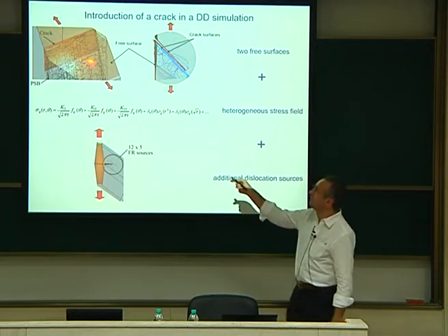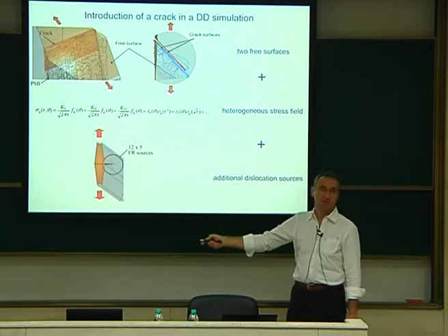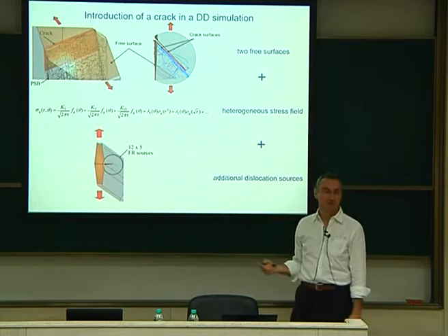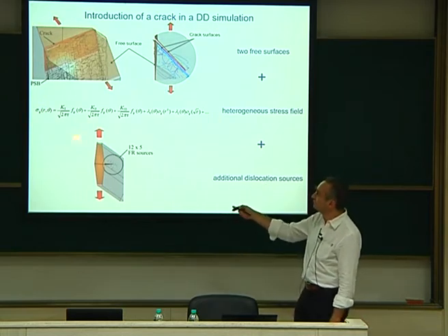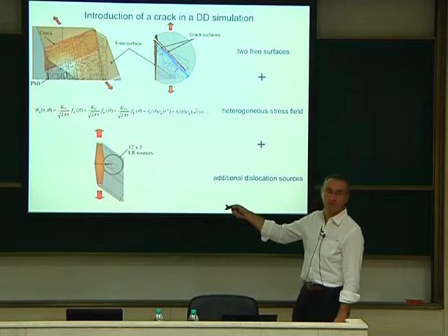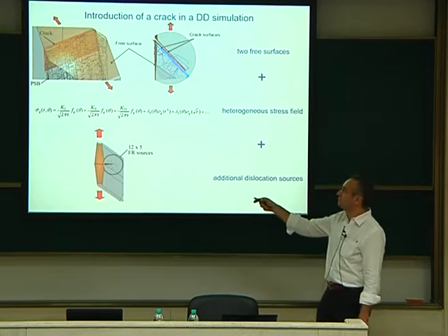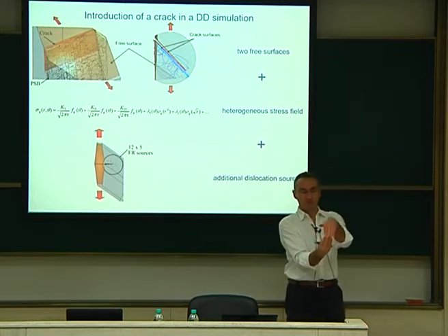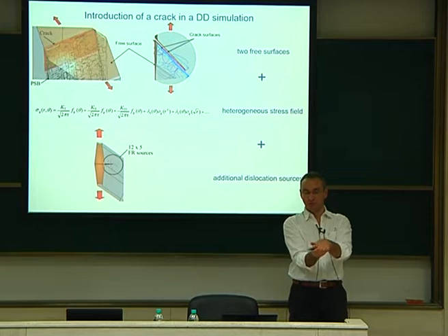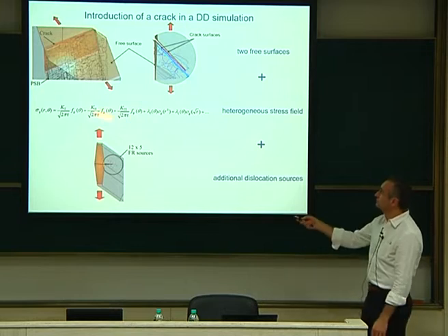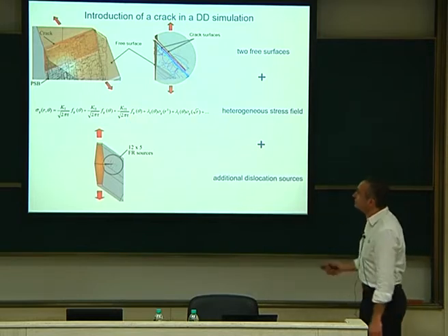What we do is that we put the crack as if it was an infinite 2D crack. So for an infinite 2D crack, you have very nice analytical fields in textbooks, which look like this, where you have the mode 1, K1, the stress intensity factor, divided by the distance to the crack tip times the functions f. The same for mode 2. Let me remind you that this is mode 1, this is mode 2, this is the crack tip, and mode 3 will be this. So you have the three modes like that, which depend on such a formula. So this is what we put.